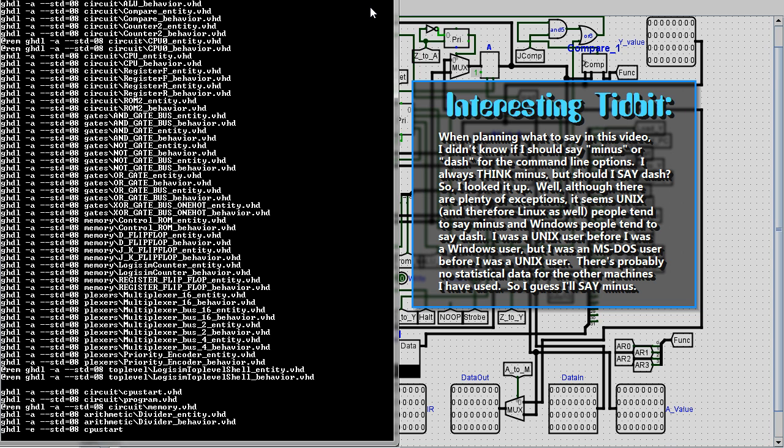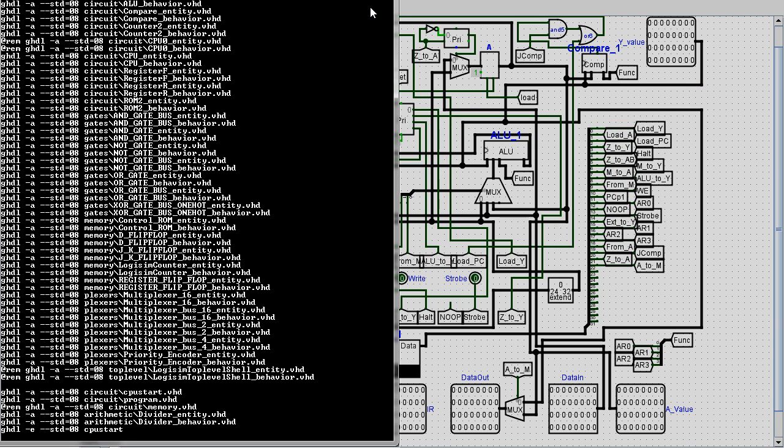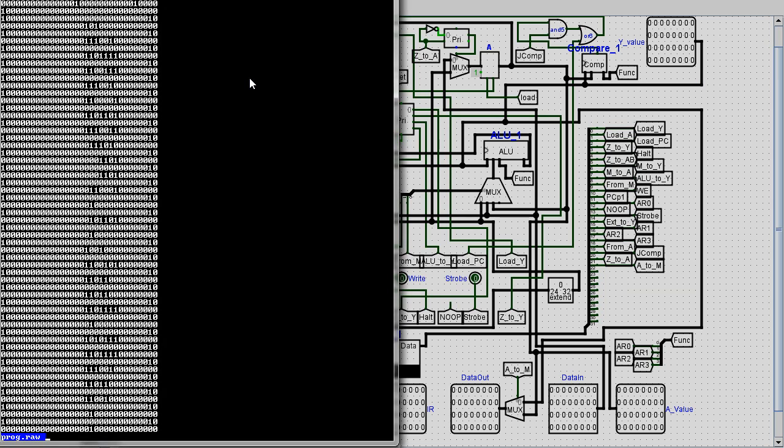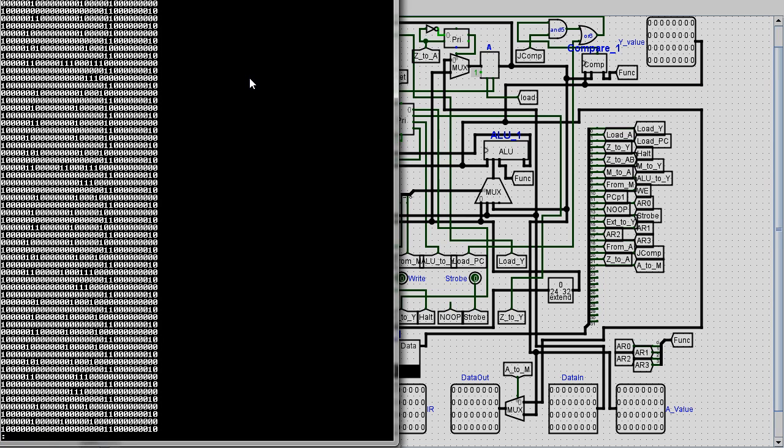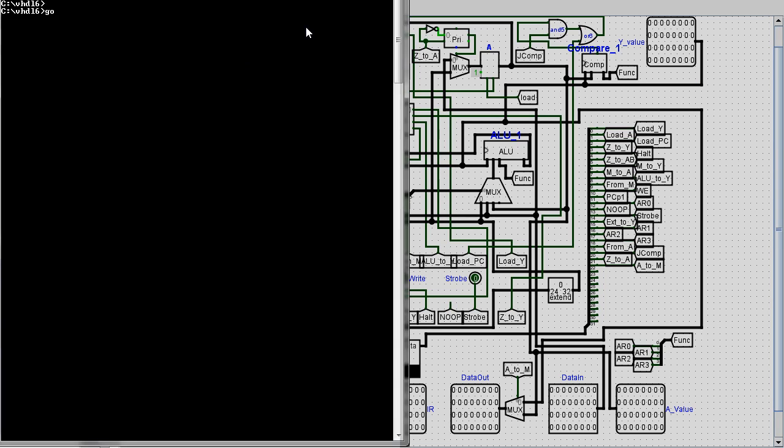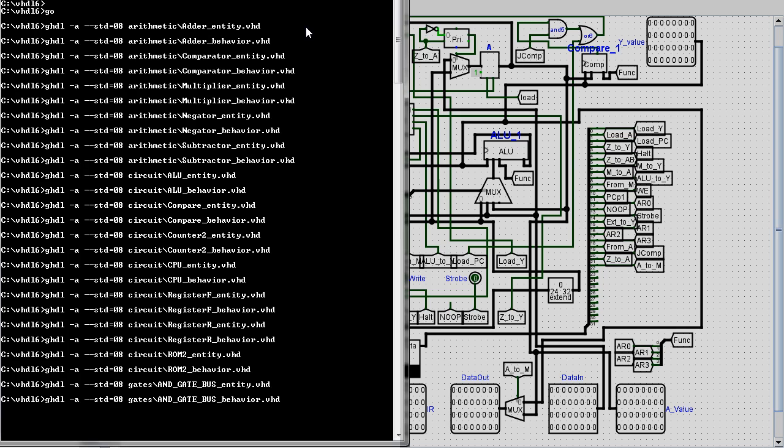If you have the Linux version, you can compile to an executable and even link in object files created from other languages. In that case, you could do things VHDL can't do. I commented out the components I previously mentioned I didn't need, the base and top level components as well as CPU 0. And here's the program I'll run with my CPU. Now I'll compile it.